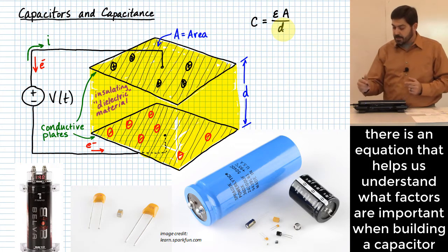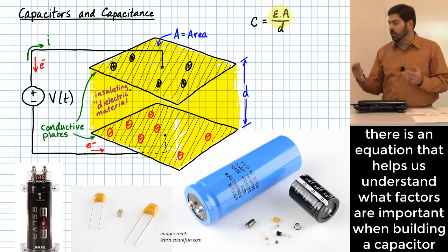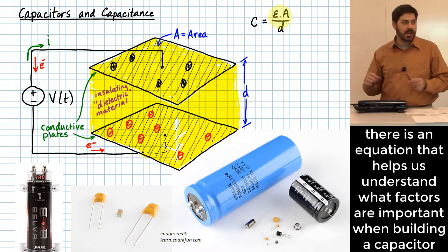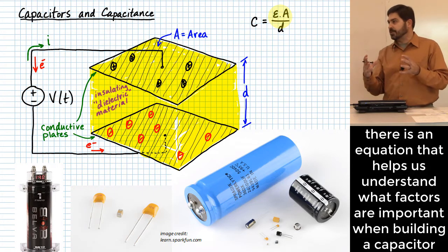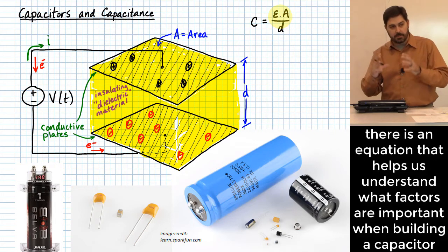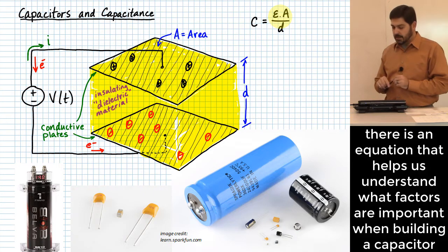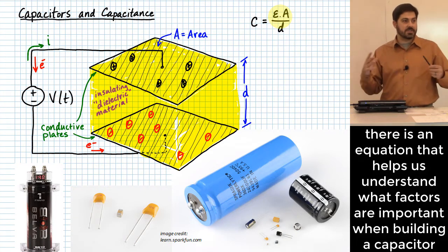They also do some things with different kinds of material that might have higher values of permittivity, right? You can only get so much out of that, but there are some efforts to figure out how you can increase your permittivity so that you can have a certain amount of capacitance for a relatively, hopefully, smaller package. Generally, you're trying to make your package smaller for how big your capacitor is. That's usually the goal. But what else can they do to try to increase capacitance without having to increase package size?